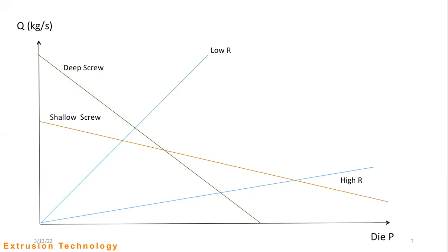Part by part of the extruder, now you can guess how we can use this extruder, right? So if you are going to develop any food product, a plant food product, you can select or even imagine the flight height and the surface of the barrel and the screw characteristics. Likewise, you can determine the pressure, shear, things like that, right?